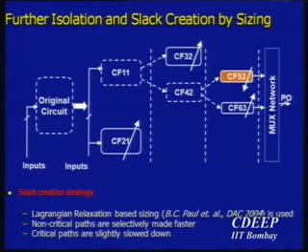So how does it help? Now, when I know this input condition is valid, I know which sections of the logic are going to be active. And that lets me do 2 cycle operations as required. So if I have a number of inputs, x1 is equal to 1, x2 is equal to 1, x3 is equal to 1, and so on, and I assign probabilities to those, then I also have a fair amount of idea about the probability that a certain section of the logic is going to be active.